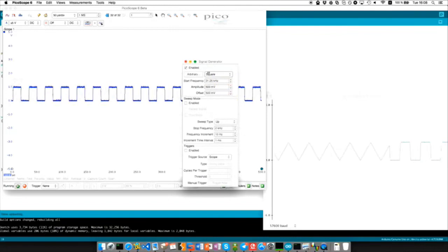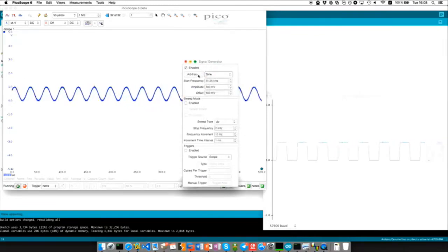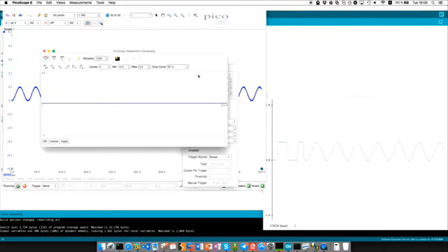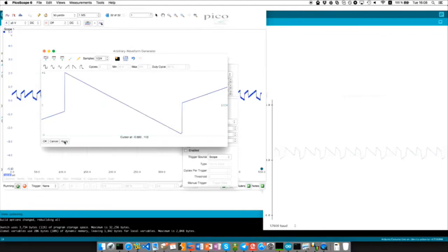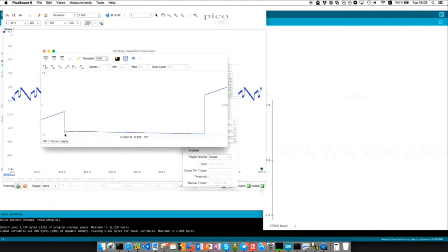As an example, we are inputting different types of signals. As you can see, they are not exactly the same because we're injecting them at 31 kilohertz, and the output is half a hertz. But you can see that with the editor of the PicoScope, we can generate any type of signal. What is happening here is that the ADC is not blocking at all the signal that should be blocked, and it's actually getting the signal as is and multiplying it by 2 because we are in gain 2. So this is a weird scenario. Here we kept playing with the signals. As you can see, it's not exactly the same because it's sampled and there are some minor changes in the readings.